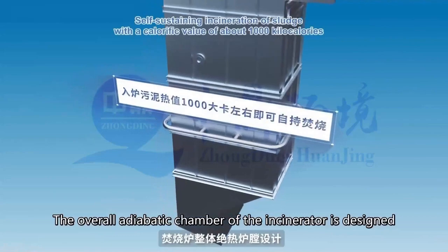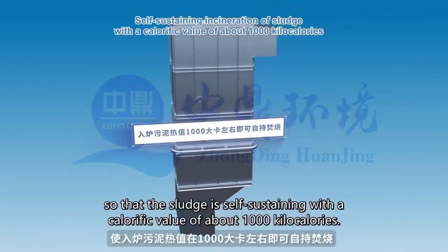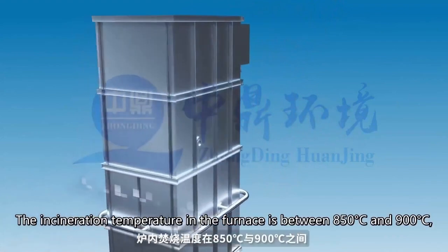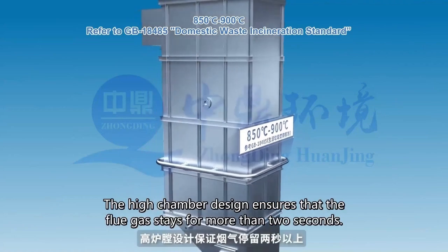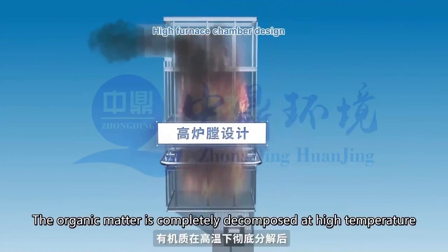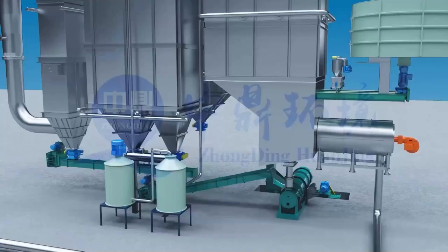The insulated furnace design of the incinerator maintains the sludge's calorific value at around 1000 kilocalories for self-sustaining combustion. The incineration temperature in the incinerator ranges from 850 to 900 degrees Celsius, meeting the national standard for municipal solid waste incineration. The high furnace design ensures that the flue gas remains for over 2 seconds, then discharges from the upper outlet after complete organic matter decomposition at high temperatures in the fluidized bed incinerator.